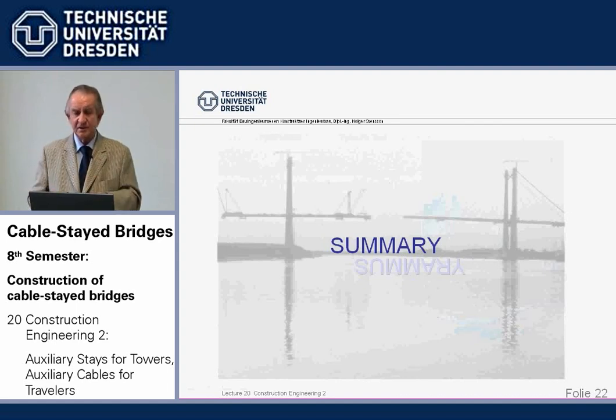It has less high loads. And as we mentioned, depending on the span to depth ratio of the cantilever, if we have a very deep beam with small cantilever lengths, we may be able to lift very heavy elements without any auxiliary tiebacks. Thank you very much.